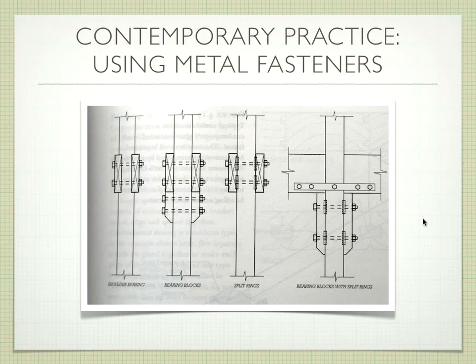Say we're doing just a large beam, a 6 by 10 beam. We have to have a tree big enough so that we have a clear 6 inches by 10 inches for however long we want the beam. So say it's 50 feet tall. We need a tree that 50 feet up in the air is at least 6 inches by 10 inches. Part of the problem is we really want a tree much bigger than that, because by the time we mill off the sides, if it's just right through the center of the tree, we're going to have that core and it's going to bow and twist on us, as opposed to if we were able to carefully conceive of where we cut that beam from within the tree itself.